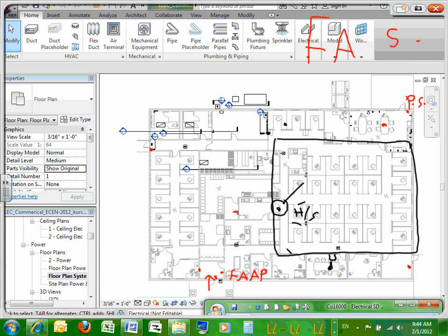And false alarms mean fire trucks screaming out to your building, and then all of a sudden there's nothing going on, and they go to that annunciator panel. Because we have an addressable fire alarm system, that means it's a smart system. It knows what's going on. They might come in here and it might say dirty smoke detector in mechanical room, and the fire trucks just came out to your building for nothing. And I think after a certain number of runs, they start charging people. Yeah, after that. I can't remember how many.